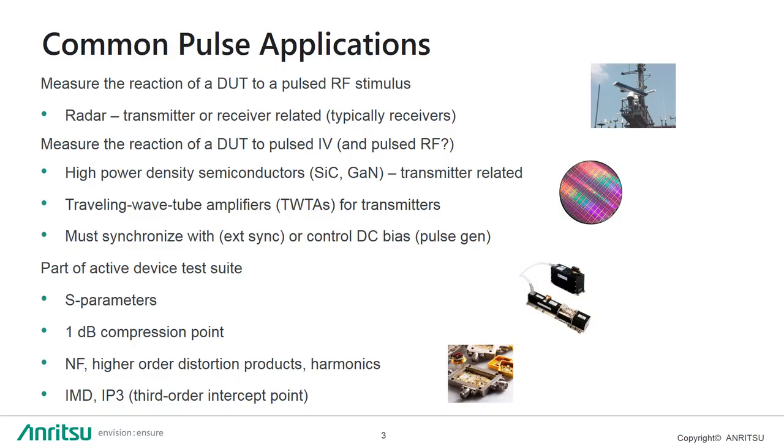Pulse test parameter and related measurements are critical for many common applications. The tests of a system or subsystems designed to operate in pulse conditions. A pulse system and subsystem measurements that may be needed examine phase and amplitude distortions at pulse onset or droop later in a pulse, as well as in cases where the subsystem was designed to operate pulsed. Or the measurement of devices and components that are designed to operate in pulse conditions. Device characterization, where pulsed operation is required for thermal reasons, for example, unmounted power devices. Or device characterization, where pulsed operation is required to explore certain device characteristics. Trapping and thermal parameter characterization are two common tasks that benefit from pulse measurement.